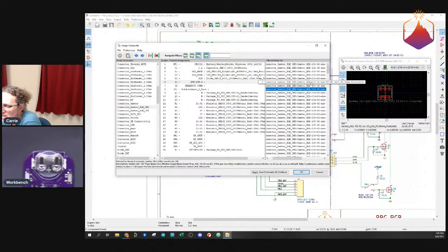But honestly, I think I would just want to make my own, because the other thing is I want to make sure that the silkscreen outline is big enough to encompass the actual connector. If I make my silkscreen smaller than the actual connector, then I might forget to leave enough room around my component and I might encroach other components on it. Then you'll go to put that connector on and there will be other components in the way. And that's no good. So I like to make my silkscreens actually representative of the space that the connector or the component takes up on the board. So yeah, I will look for that later.